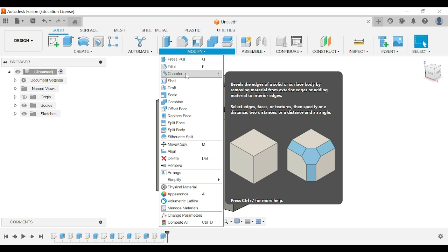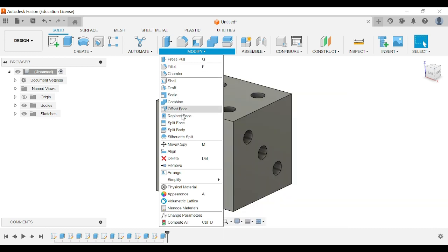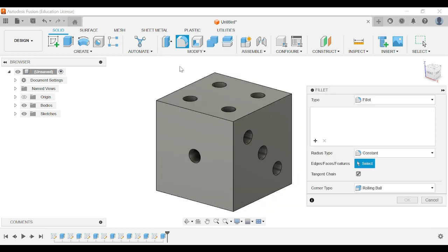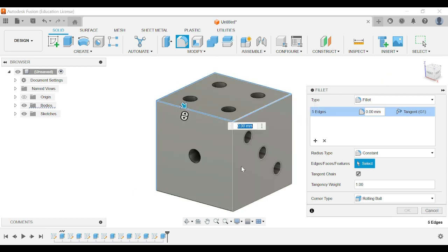How do I explain it? It looks like that pretty much, what you can see in that image right there. You've got other tools as well. Don't worry too much about all of that other stuff, but let's go fillet. And what we can do if we click on fillet is we can click on each of the edges, every single edge. If we go fillet and click on all of them, oh, that's not what I wanted, unclick that.